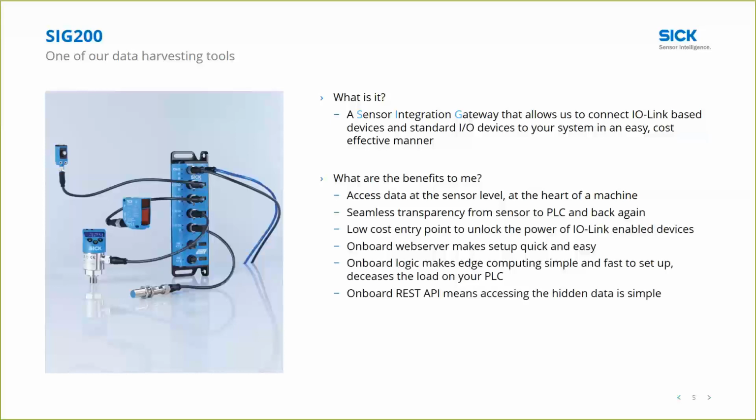This SIG200 has a REST API on board, which means we can communicate over an HTTP protocol, and we can get access to the IO-Link data over that platform, which is quite a useful way to get access to this information.